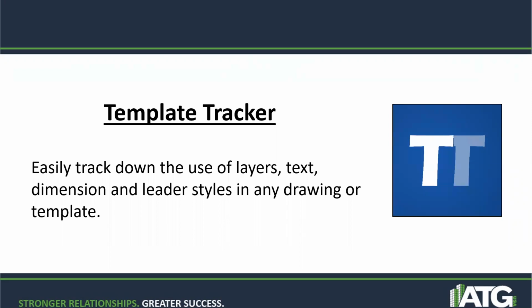And without this tool, really the only way to figure out if a style is associated with a layer is a very brute force trial and error approach. This tool makes all of that mapping super easy to identify and also super easy to change. So we'll see that inside the software, but basically we're just trying to get a feeling for what layer has, or what Civil 3D style, now in the Manager Suite, has a particular other style associated with it, so that we can make sure that everything's mapped correctly, or even for the process of removal.